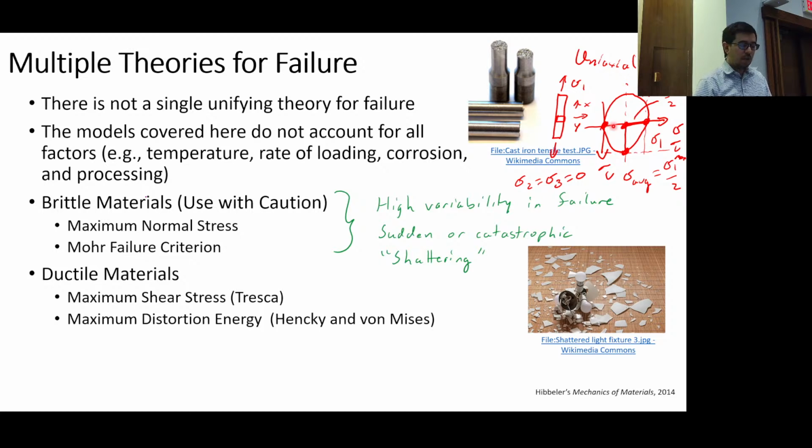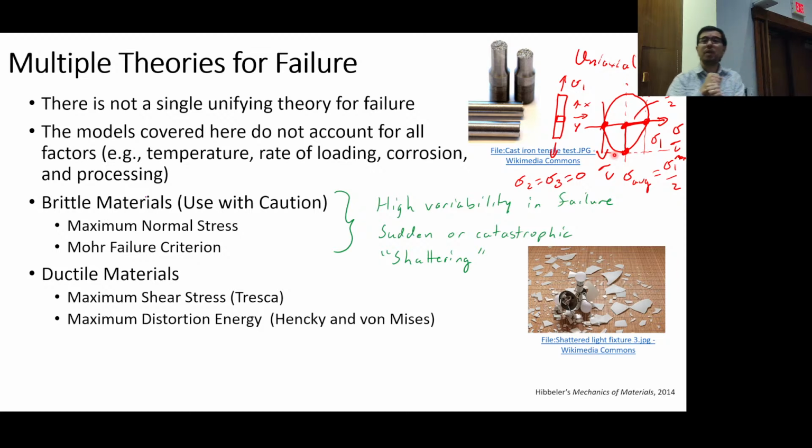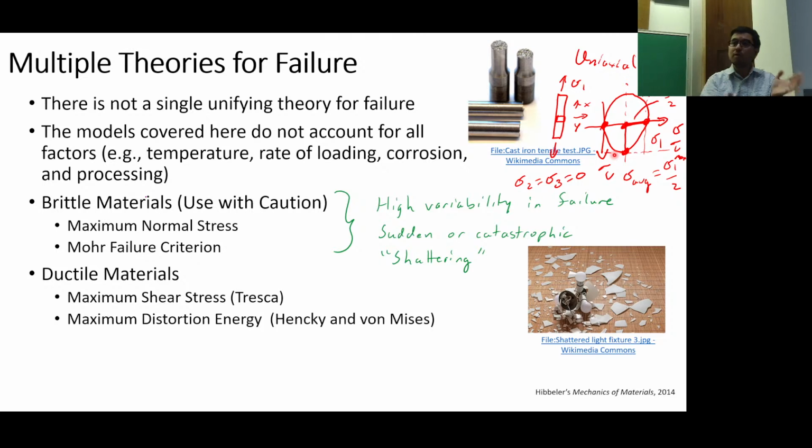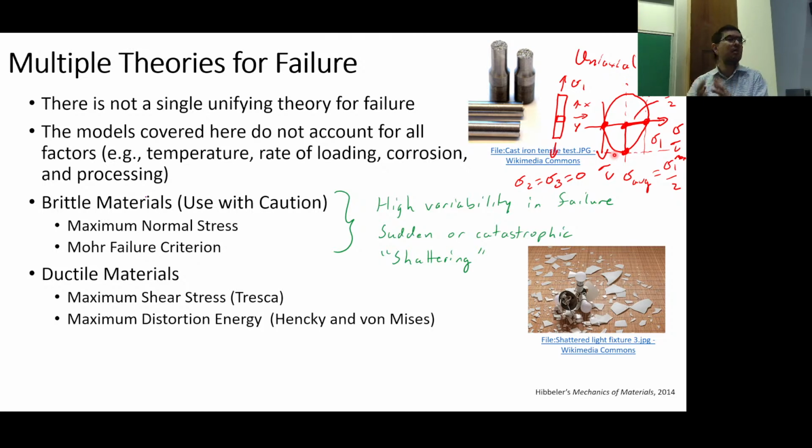And so I could go through the exercise of drawing the 1-2 circle, the 1-3 circle, which I actually have, right? And then there's going to be another circle, the 2-3 circle. But that's just a dot, so it doesn't appear on the Mohr circle, right? So this is a case where the maximum in-plane shear stress that we're used to drawing, or we learned to draw first, gives us the same result as the absolute maximum shear stress.